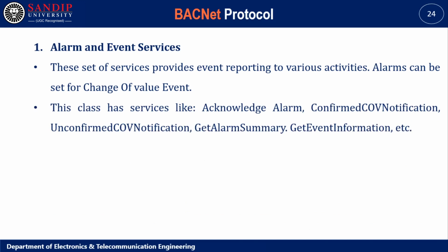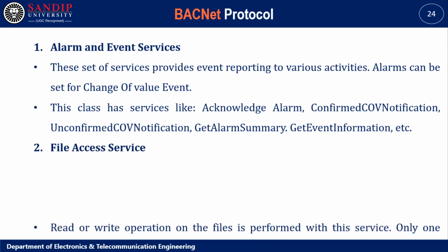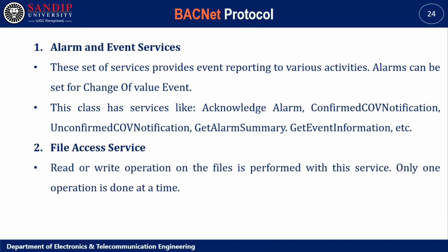This class has services like acknowledge alarm, confirmed COV notification, unconfirmed COV notification, get alarm summary, get event information, etc. File access service: read or write operation on the files is performed with this service. Only one operation is done at a time.